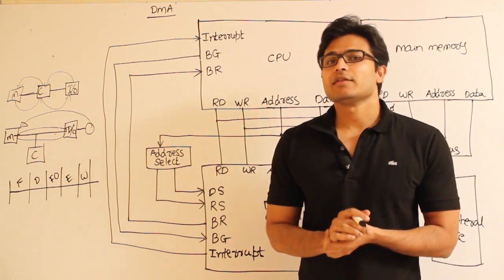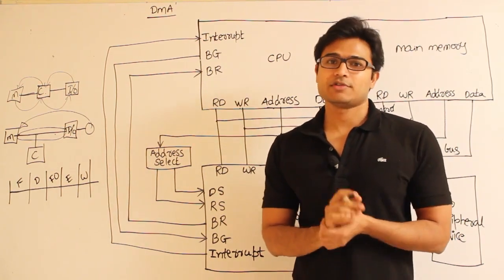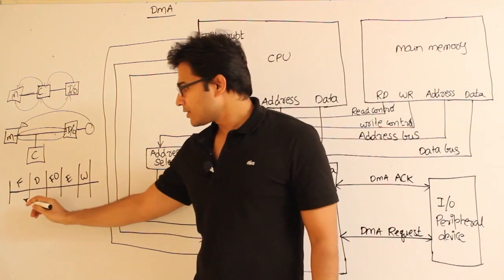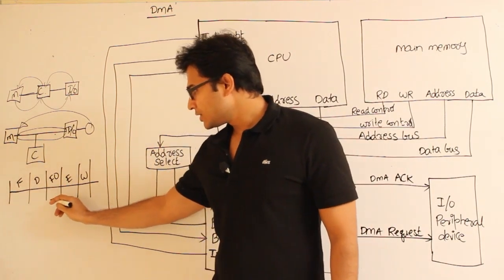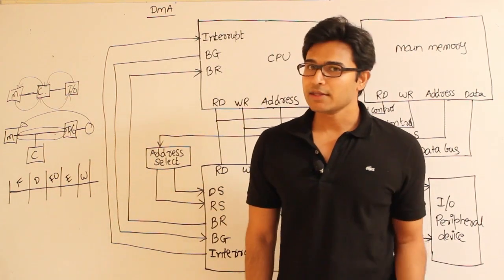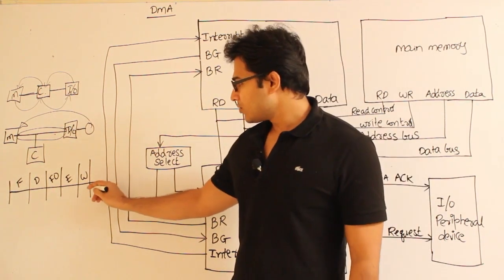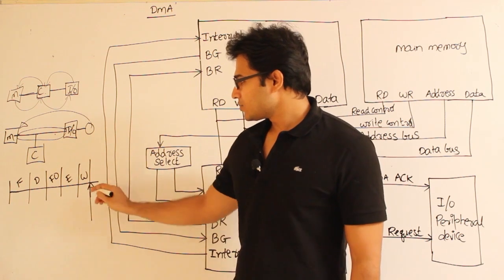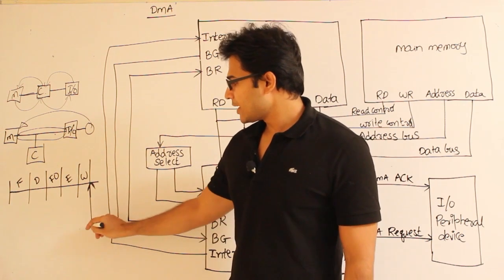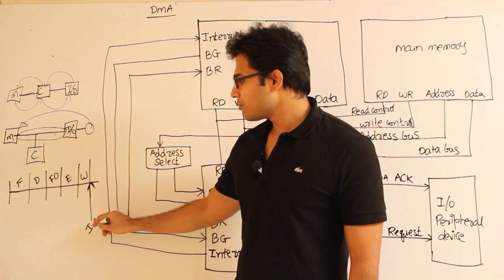Now whenever we get an interrupt, when are we going to process it? We might get the interrupt signal anywhere during the instruction cycle, but we are supposed to address it only at the end, only at this point, right? This point is called the interrupt break point.